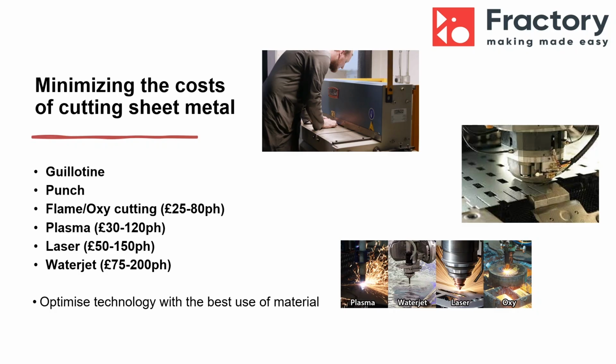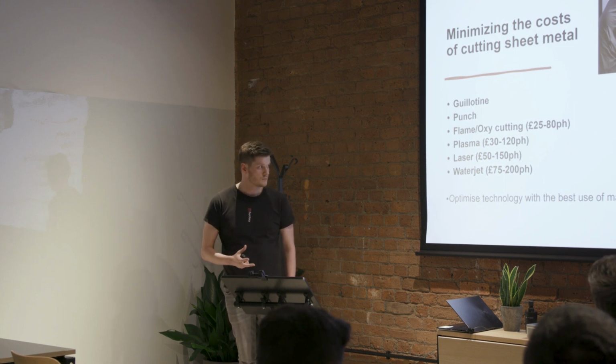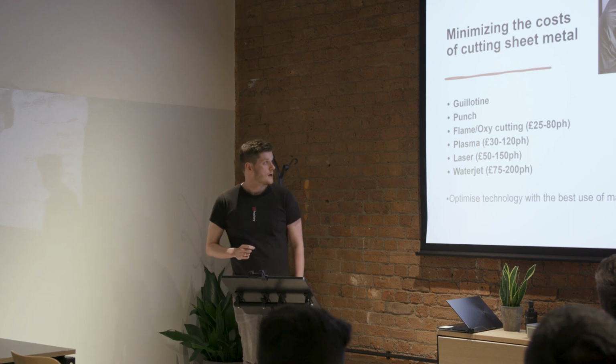The next thermal cutting is laser. This is typically for your thinner gauges. It's an energy beam which is intensified by computer-controlled mirrors. It gives a very precise and smooth cut, typically on the thinner gauge materials. It tends to be more commonly used in sheet metal fabrication just because of the higher precision of the cuts for a relatively good price and the cut quality itself.